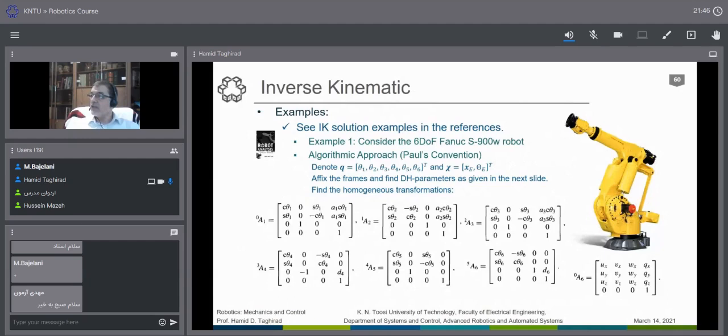We usually have such an extra link in the robot. This is generally used because of a very interesting mechanical idea: if we have a parallelogram architecture, as you see here, to move the base, you can put the motor right on the base, so you don't move the base motor when the robot is moving.